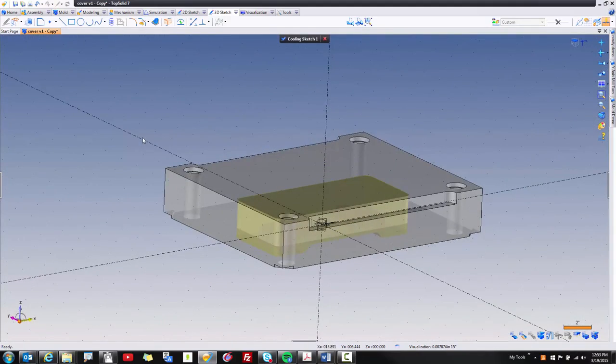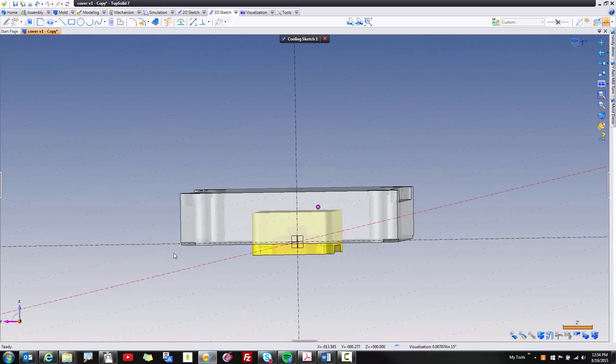We're going to use a 3D sketch to drive the center line of the pipe circuit that we want to put in. To begin with, I'm going to start by using the point on shape command. With point on shape, I can just select directly on the face of a model, and the software will constrain for me automatically a point that stays in contact with that face.